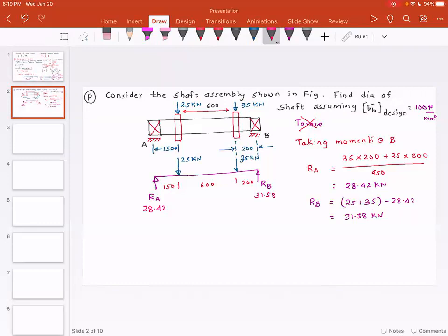So I'm sure you studied in mechanics of materials, or EGR343 and EGR444, that the bending moment is maximum where the shear force changes direction or changes sign. So when shear force goes from positive to negative, that is the point where the bending moment is maximum, because the derivative of bending moment is shear force. So how do you draw a shear force diagram?